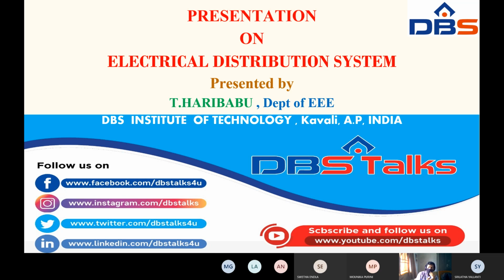To find the average power loss, we know the loss factor definition. Loss factor is the ratio of average power loss to the power loss at peak load. We know the loss factor and we know the power loss at peak load. From the given problem, loss factor is 0.15, power loss is 80 kilowatts. Therefore, average power loss is the product of loss factor and power loss at peak load, that is 0.15 into 80, that is 12 kilowatt for 3 phase.